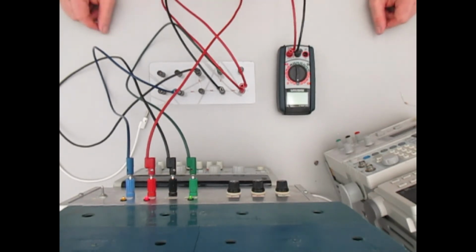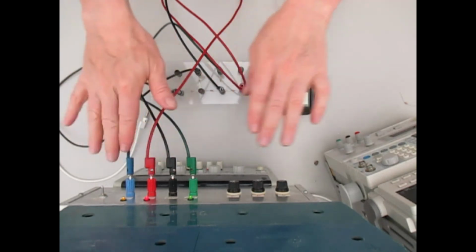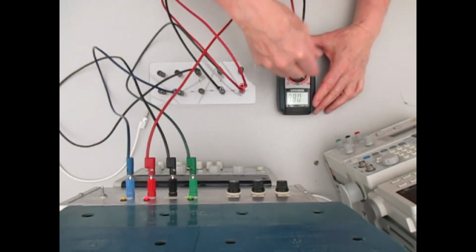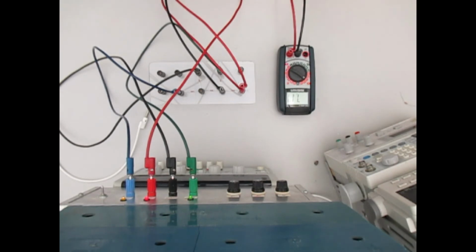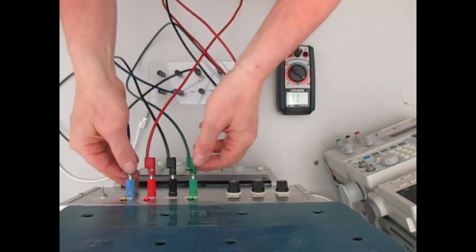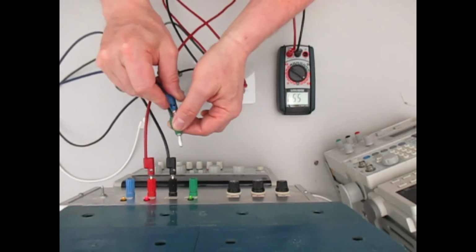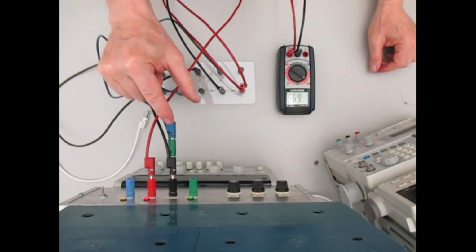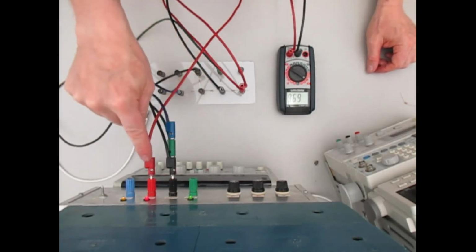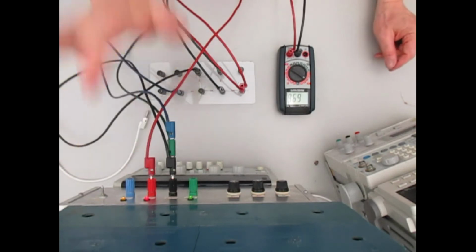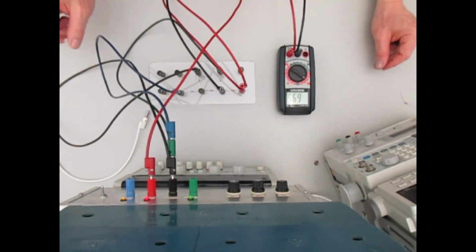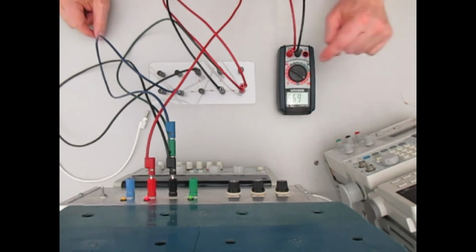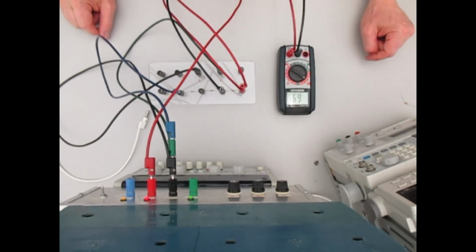So again, what you're trying to do is fill out the table. What we're doing is the R1 values. Okay, so right now I've got them. Well, what I'll do is we'll do it in the manner of the table, right? So right now I take these two leads, the E2 and E3, and put them on the ground. And now it only leaves E1. Okay, so this is R1, E1 is 6.95 volts.